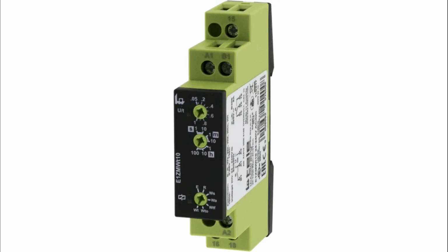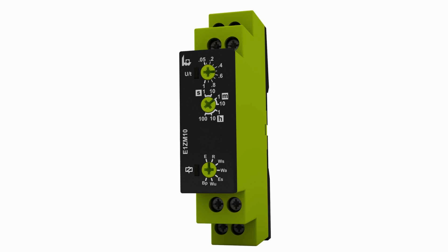Delay time setting. Adjustable time delay relays typically feature controls or settings that allow users to adjust the delay period. This adjustment can often be made using potentiometers, switches, or digital interfaces, depending on the design of the relay. Precision control. Some time delay relays offer fine-tuning capabilities, allowing users to set the delay time with high precision. This precision control ensures that the timing matches the exact needs of the application, minimizing any potential errors or inaccuracies.